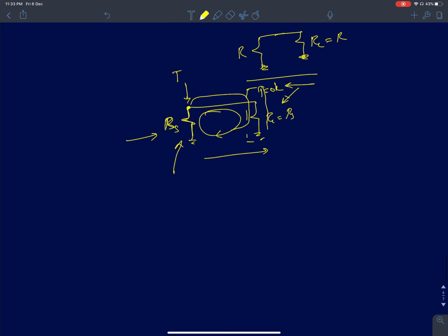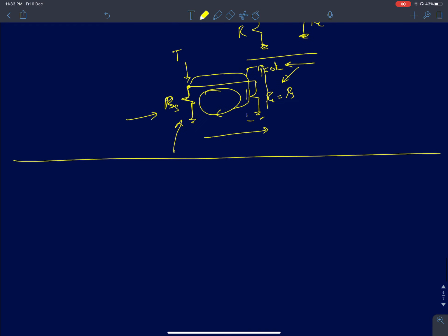So the takeaway, the main important point, is the term available noise power. It's more of an intuitive term; real noise cannot deliver power to a load. And that is kT. The units is watt per hertz. So if you know the bandwidth of the RF system, then multiplying by the bandwidth, you will get your available noise power in watts. You can also express this in dBm.